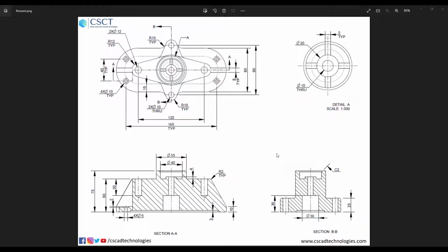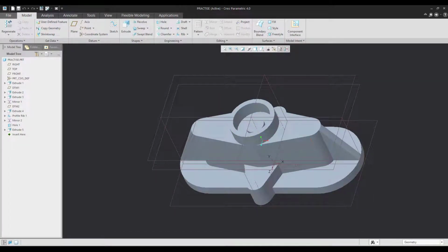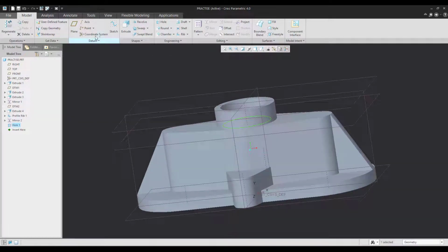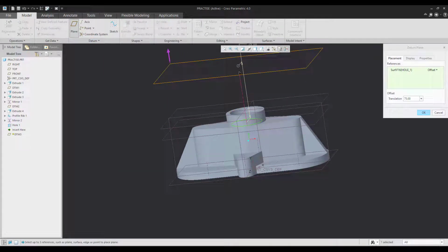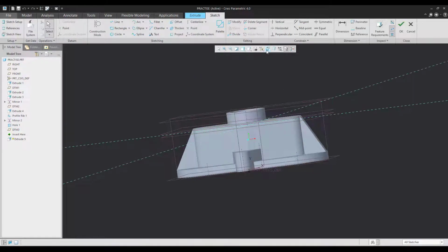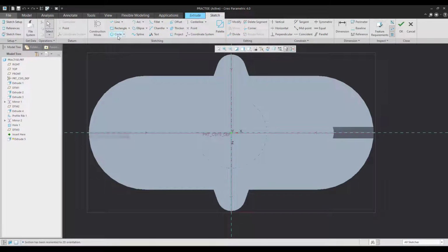Now, let's continue to make these wings. These wings are actually at 4. So as a reference, let me try to take a new plane from this face towards the other side and give it as 4. On this face, I'd like to make the cut. Now I know the center reference is actually 20, which I have just deleted.